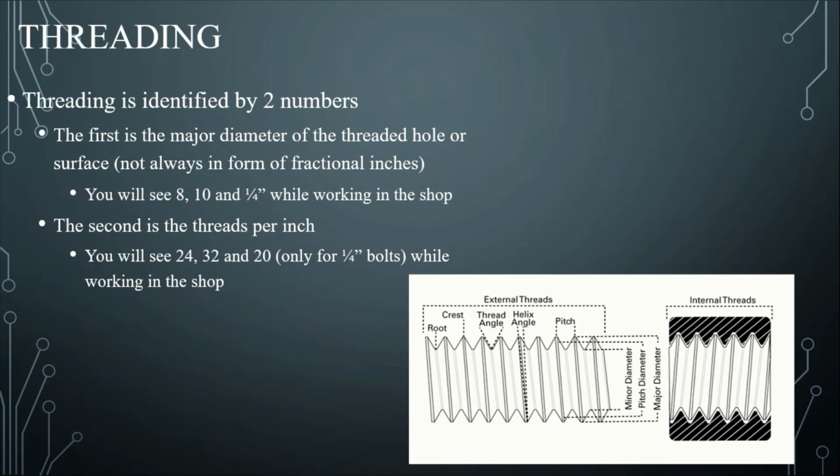if I were to take a 10-32 bolt and try and put it into a 10-24 hole, I would end up destroying the threads on both of the threaded areas, and I would have to redo the threading, which isn't always that enjoyable.